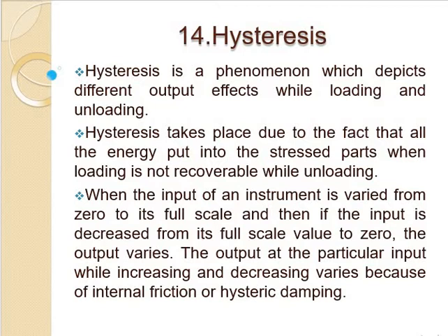So when this instrument is varied from 0 to full scale, and then the input is decreased from the full scale value back to 0, the output will vary. Generally this output differs between increasing and decreasing because of internal friction. So then it is also called hysteresis.